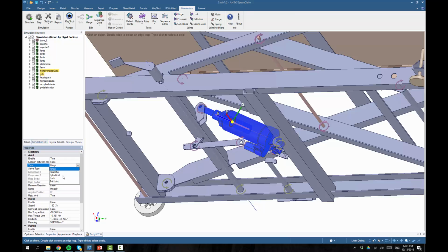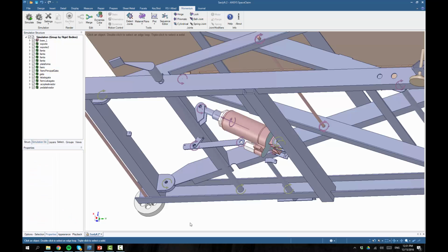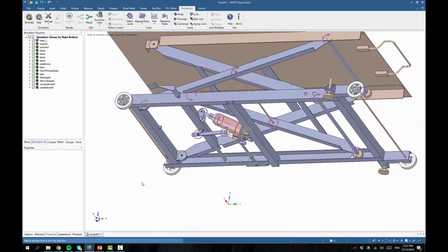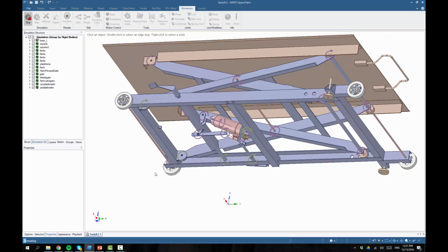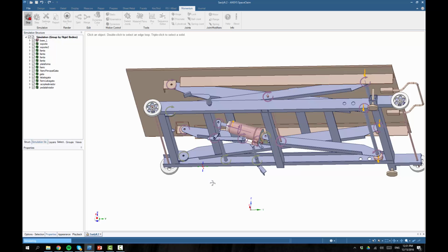But with this tool, you should do the opposite, because here you can handle all of the redundant constraints of your real design. So you bring in more of reality in your simulations. And that, in turn, suggests that you should be more careful with how you set it up. You should pay more attention to how it actually works, so you don't add constraints that are not part of your real system. So there, now turned it into a cylindrical constraint. And we simulate, and the table falls down. Very good.